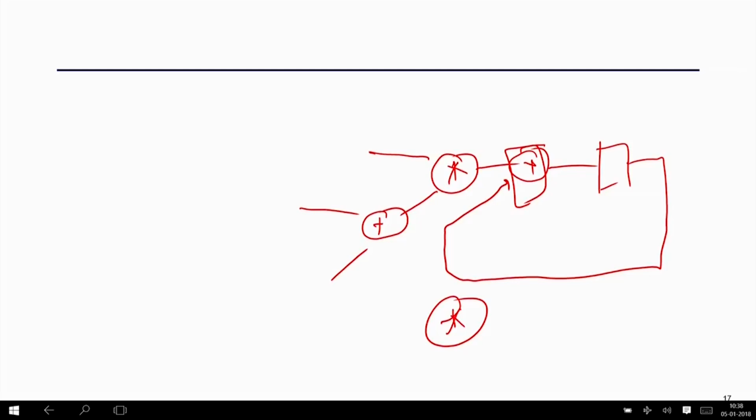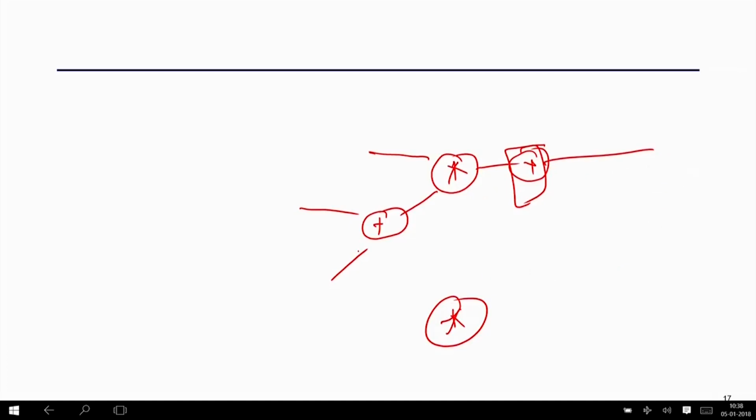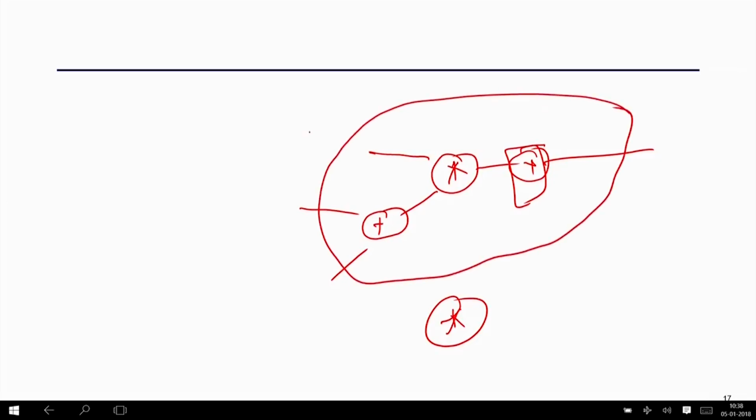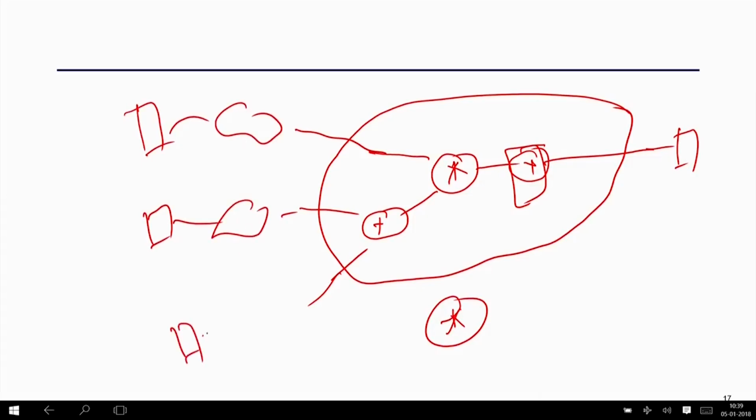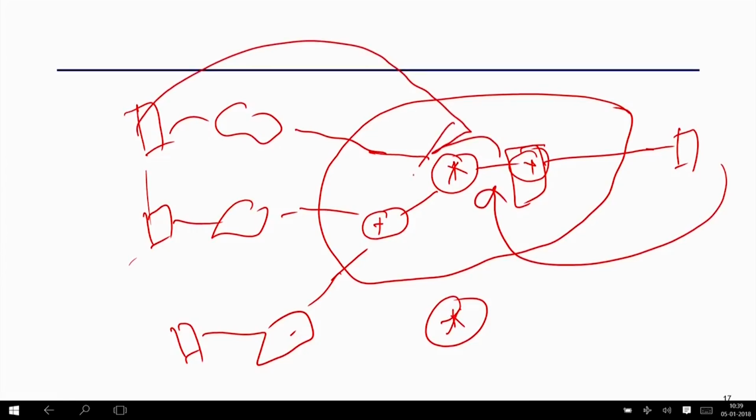So, you basically start from a multiplier and try to enhance the structure as much as possible. Suppose you figure out that I have a pre-adder as well as a post-adder, then you can have this structure. This is the MAC structure we are going to preserve, but there is no register here. Then the next objective will be to do some local retiming, just to move nearby registers. There may be some registers here, maybe there are some other logics here, but finally there is some register. You try to move these registers into this structure, so that you can pack those registers as well into the MAC structure.